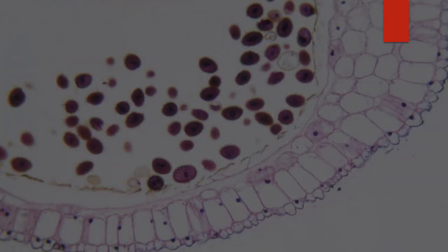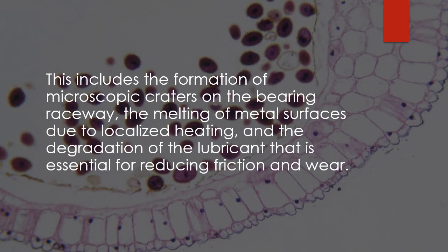This includes the formation of microscopic craters on the bearing raceway, the melting of metal surfaces due to localized heating, and the degradation of the lubricant that is essential for reducing friction and wear.